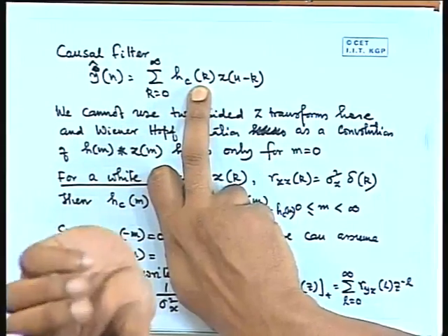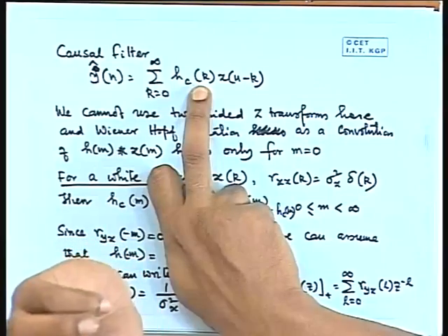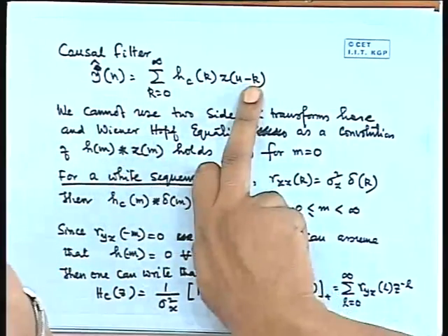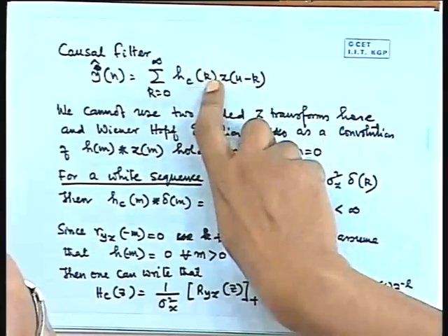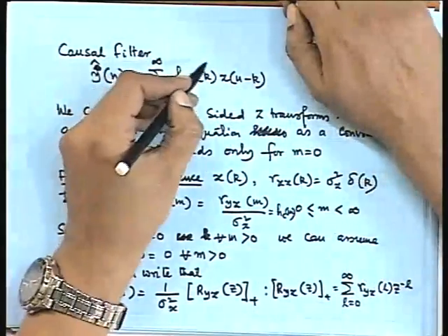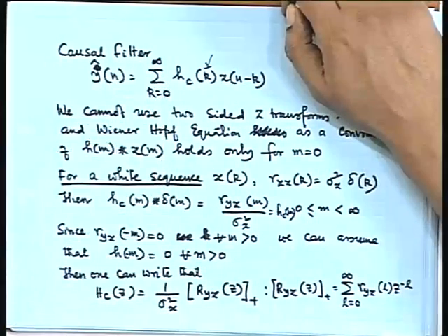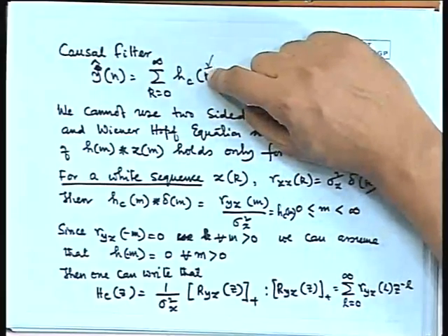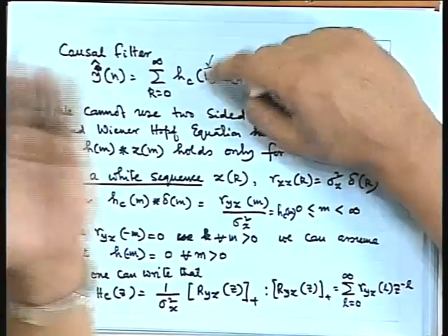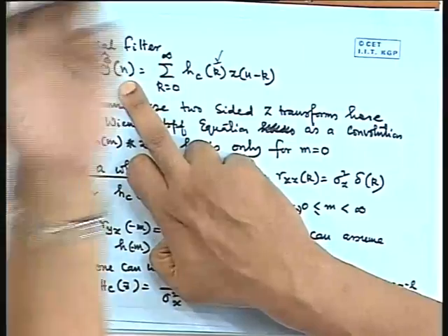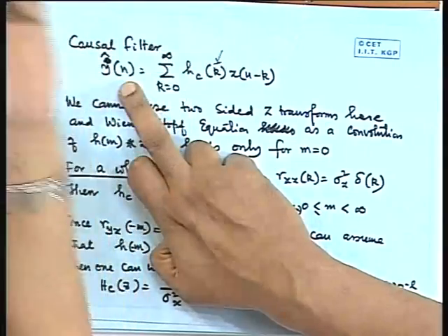You are trying to solve for a filter. So that filter must satisfy this equation, and this equation is defined, that is your filter, it will be a causal filter. So these are going to be 0 for k less than 0, right? Which means that now obviously if you have this equation, you cannot write a Z transform equation for k equal to minus infinity to plus infinity. You cannot take, because you don't have values. Okay, you cannot define autocorrelation functions.